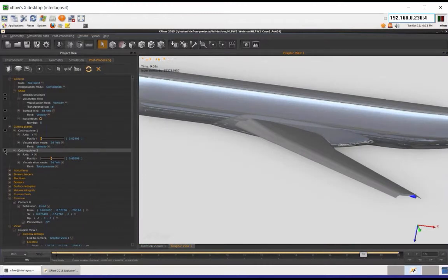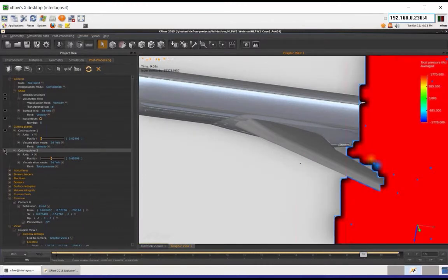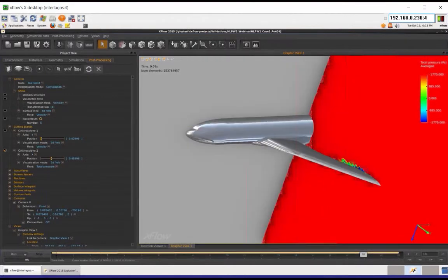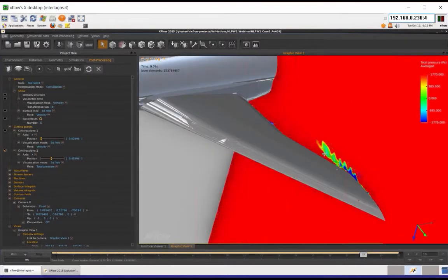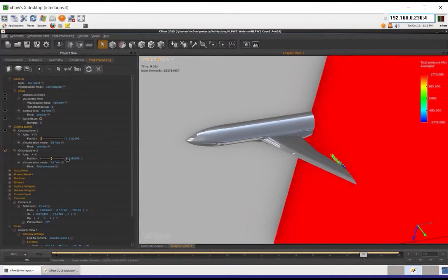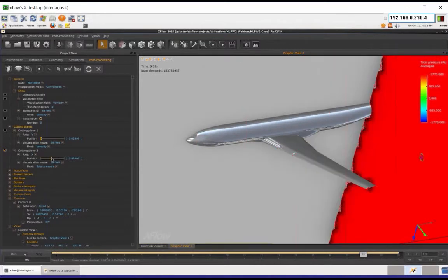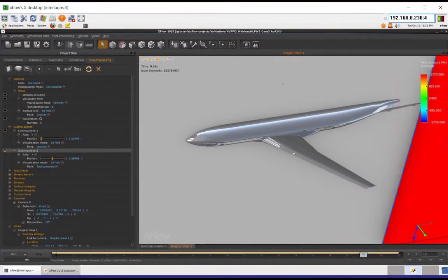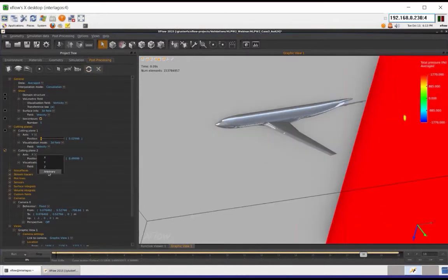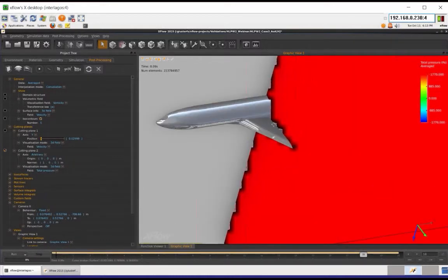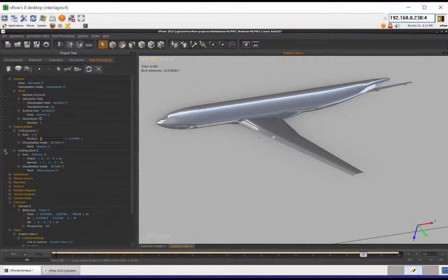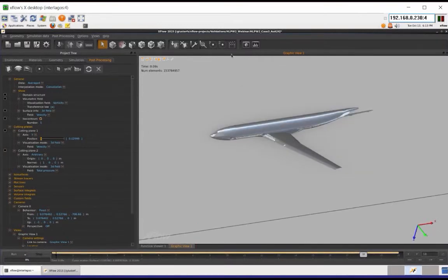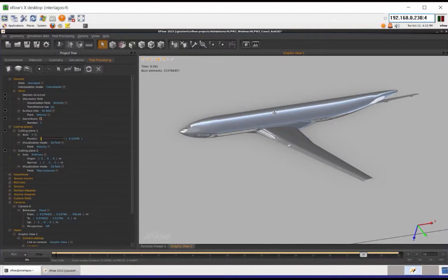And just another thing I'm going to show is a cutting plane on a different angle, in a different axis. In this case, it's total pressure, so we can see the total pressure losses due to the wake of the wing. In this case, you can just slide the cutting plane up and forward and select your visualization plane, and you can even specify a specific number, which is dimensional with the dimension of the tunnel, or specify a specific arbitrary direction where you want to have your cutting planes. There are plenty of post-processing options in XFlow. You can even build videos in it. So I'll just stop here, and so we give some time for questions to the audience.